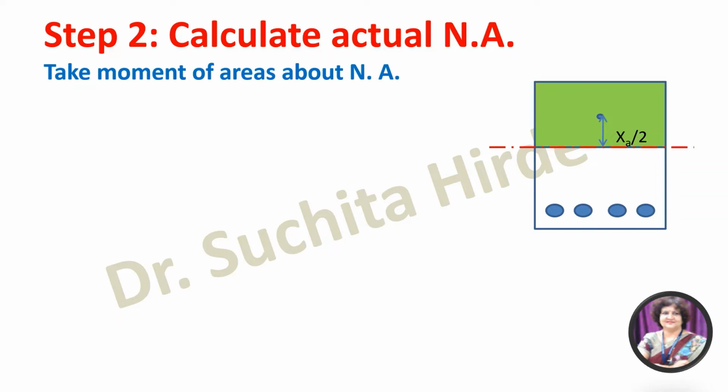First is this concrete area, and you must be knowing that in RCC beam we neglect the concrete in tension zone. That means we assume that this much concrete is only available to resist the bending moment and this steel is available. There is no concrete below this line which is in tension zone.